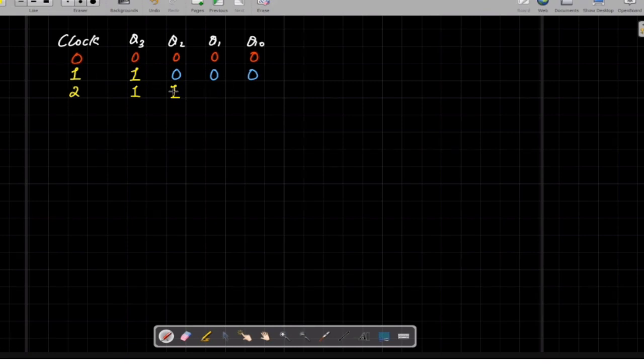and for the second, this is 0, 0. When the third clock comes, then your outputs will become like this, 1, 1, 1, and this is 0. With the fourth clock, you will have outputs of the flip-flop like this. Okay, and with the fifth clock, you will have outputs like this. First flip-flop output becomes 0.